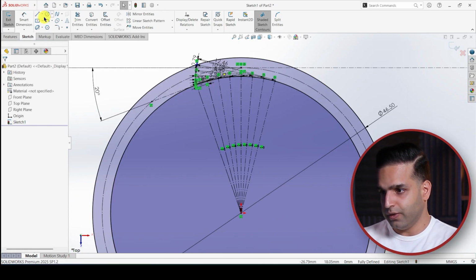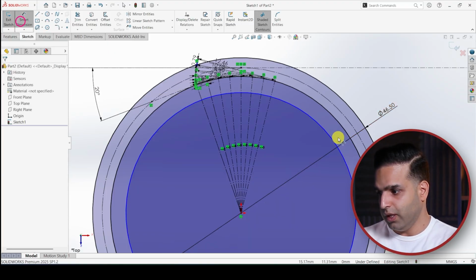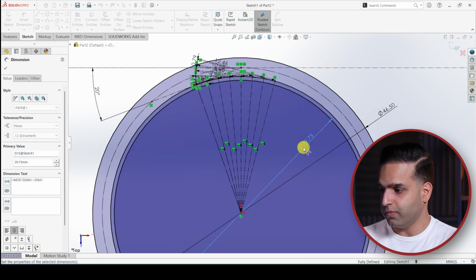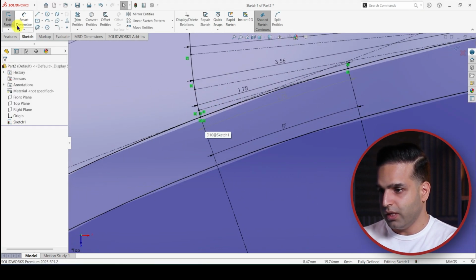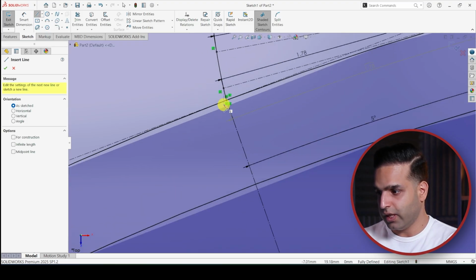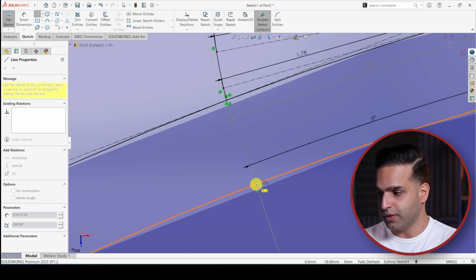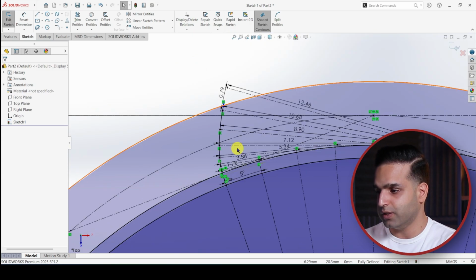Now we should draw the root circle. So select the circle again and start from the origin. And the diameter, if you remember, was 39.75. And then I select the line and draw a line from this point. Make sure that it is collinear with this line and it ends with the root circle. Select on this point and then press on escape to cancel the selection.